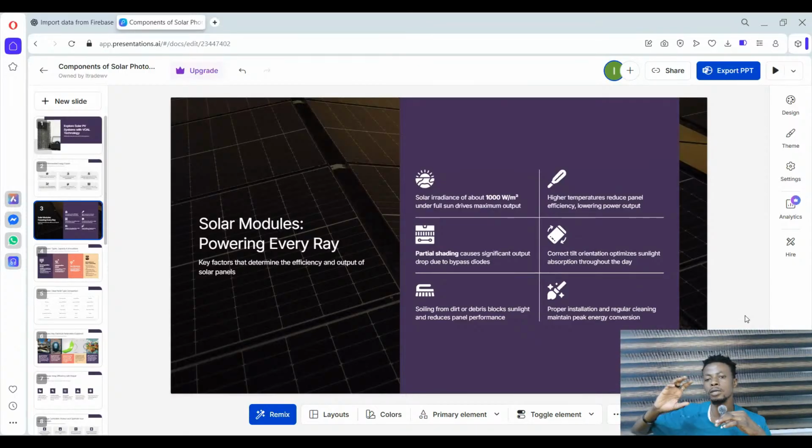So the panel has to be in a position free from any form of barrier, and placed in a place where whether the sun is setting or the sun is rising, it consistently has access to direct sunlight. Right? You don't want to have any shading effect or a barrier for the panel.